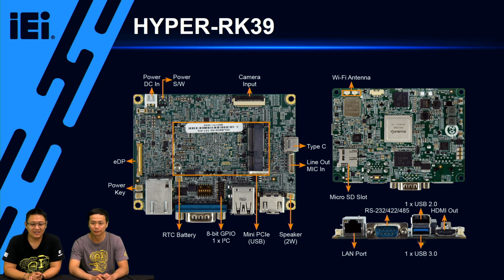However, the RK3399 is very ideal for a digital signage host system with two displays and a small RISC box PC. In fact, the applications are much more than that. If you put it on the back of a monitor with HDMI input, you will get a panel PC. We have designed a mini PCIe slot on the SPC board for an LTE module, which brings internet connectivity if your application is in an outdoor area.